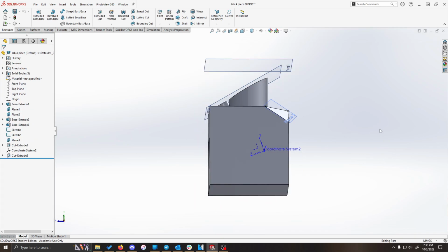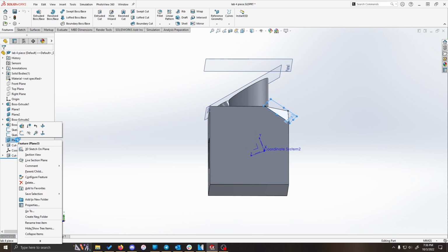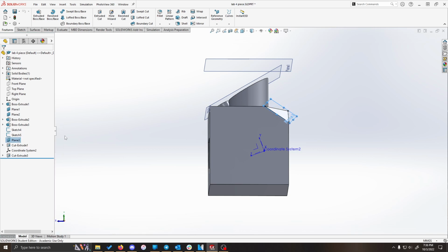As mentioned earlier, reference geometry can really clutter your part when you have a lot of it in one model. Likewise, sometimes reference geometry can be hidden from view, leaving you unable to use it. You can hide and show individual pieces of reference geometry by right-clicking on them in the design tree or in the view window and selecting the Hide button or the Show button. To hide or show all visible sketches and pieces of reference geometry, you can select this Hide All Types button up at the top. Similarly, if you can't see any of those things, you can select it once more to get them back. Lastly, for more granular control, you can hit this downwards triangle next to the Hide and Show button to pick and choose different types of things that you could see or have hidden.